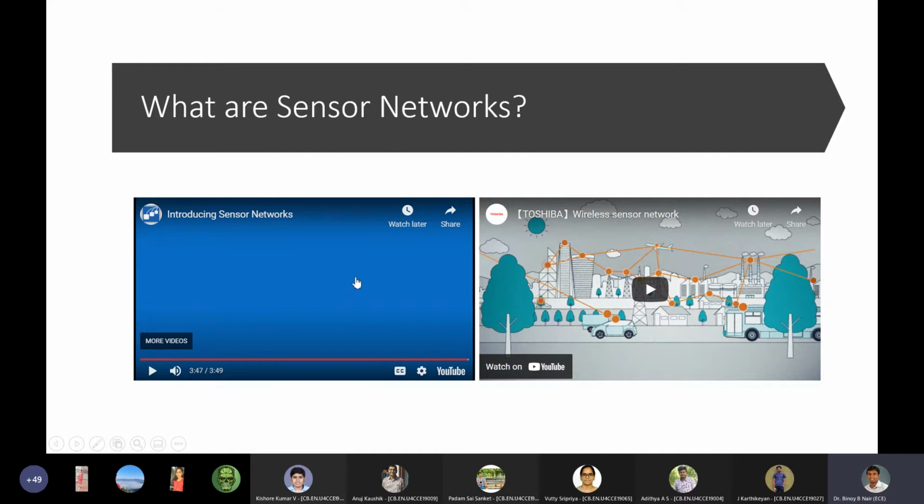So sequentially, each of those nodes will be sending data back to the central server. That is why there will be no collision or congestion of traffic in those nodes. Otherwise, because it's just a two-wire communication, there is a big chance that there will be a lot of collision of packets if there is no control. That is done with the help of a master-slave type system.